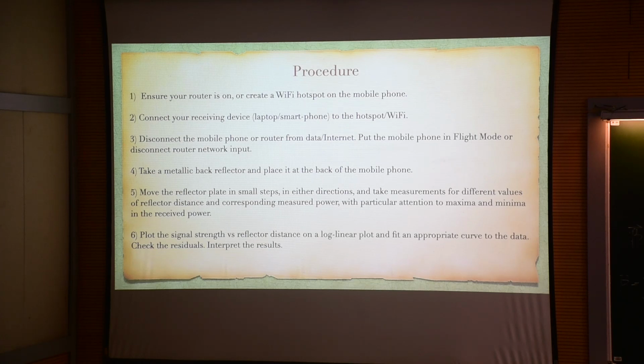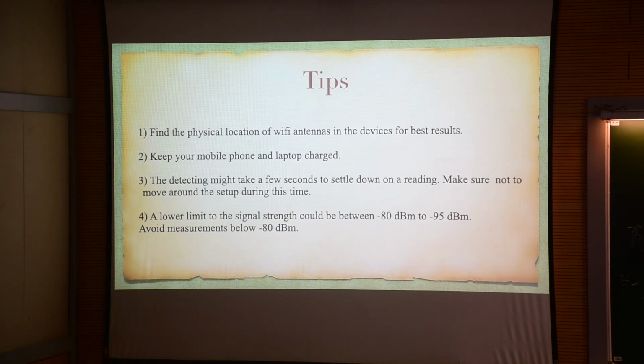Then move the reflector slowly away from the transmitter side. Okay, and see at what distance you are getting the peak or the falls in the power. Okay, so I have already mentioned to find the physical location of the Wi-Fi antenna and keep the mobile and laptop fully charged, so that during this experiment they should not drain or go out of power. Otherwise the whole setup will be disturbed, and you may not be able to get a similar result if you start again.